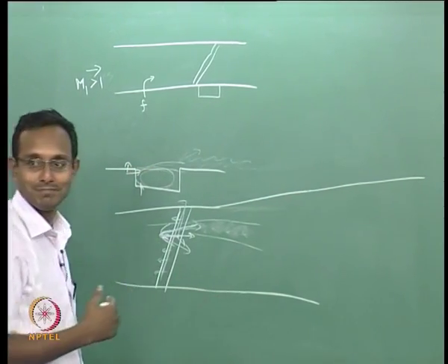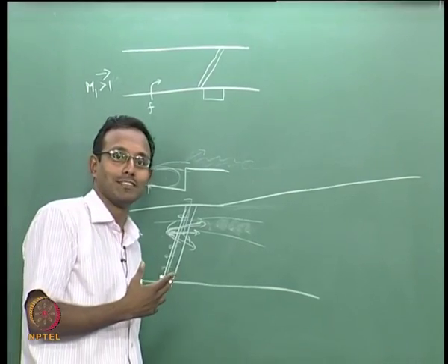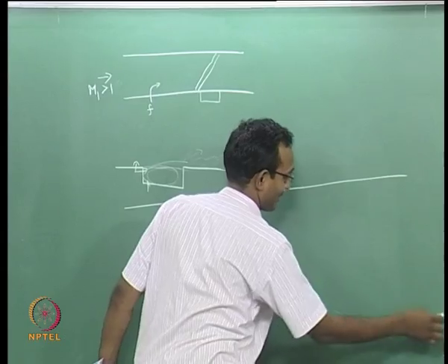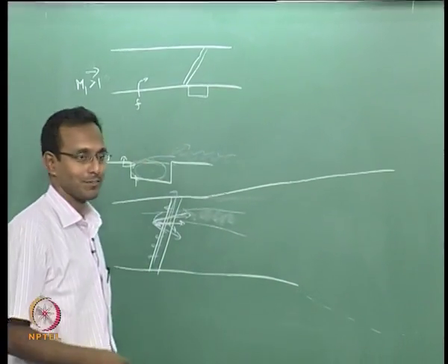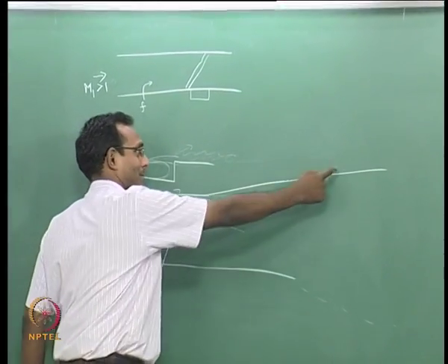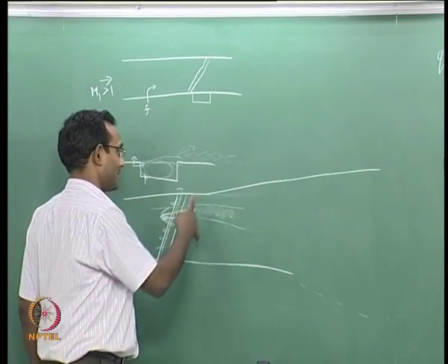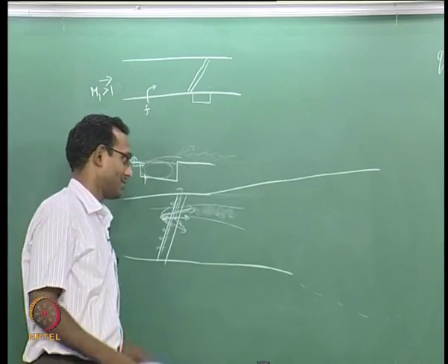If you have seen some supersonic scramjet vehicles, you will see that the nozzle is on only one side, and on the other side there will be a free jet going like this. That is also part of the design. What matters is only the pressure on the wall, so the thrust will still be there. Anyways, this is one way of handling this.